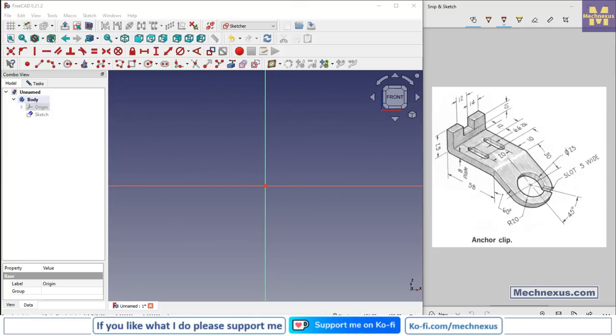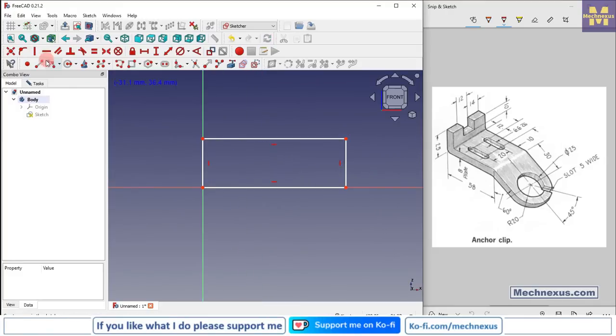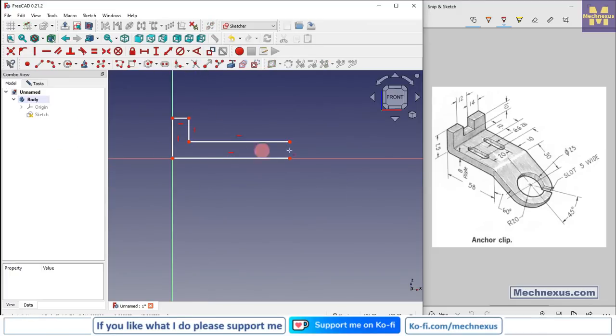So we will use the rectangle tool to create a rectangle, and then I will draw the vertical and horizontal line, and I will delete this line, click on trim, and I will also trim it, and select the line tool, create a line, make this perpendicular and join it.